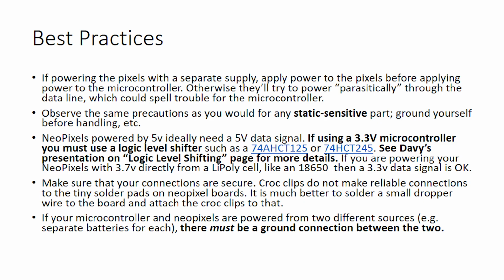Please don't do that. And this is the golden rule for all of this stuff: if you've got two separate circuits, they have to share a 0 volt line, they have to share a ground line, and share the ground line before you share anything else, or bad things will happen. And it won't be my fault, because it was the last thing I told you in this presentation.